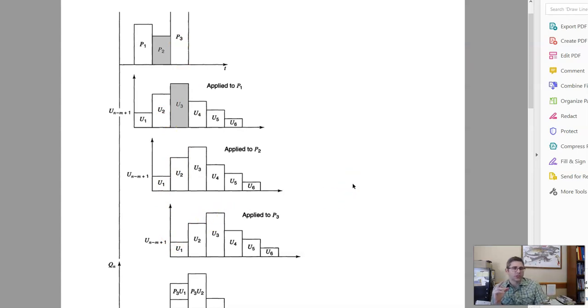And then I'm just going to multiply, because the unit hydrograph is for 1 inch of excess precipitation, by whatever the intensity in inches per hour was for this box to get the actual hydrograph associated with just that interval. So that's what's going on down here.